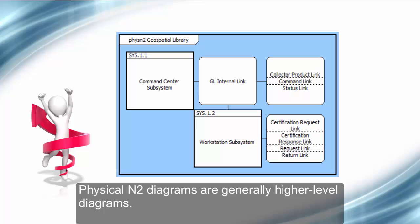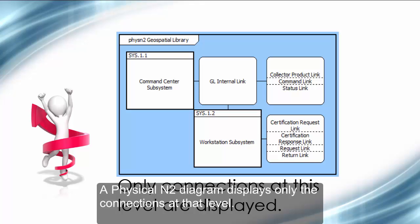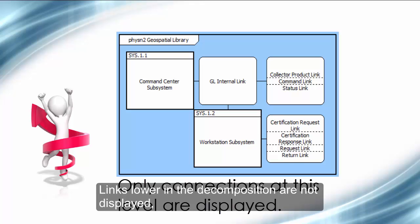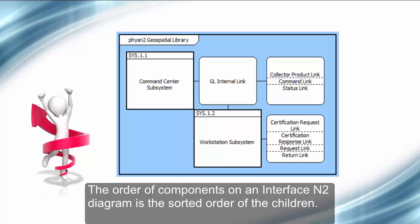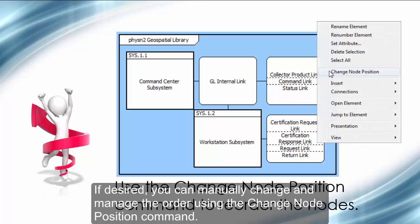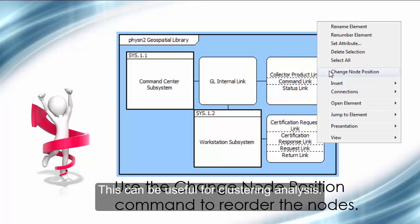Physical n-squared diagrams are generally higher-level diagrams. A physical n-squared diagram displays only the connections at that level. Links lower in the decomposition are not displayed, nor is the decomposition of components considered when placing a link in a cell. The order of components on an interface n-squared diagram is the sorted order of the children. If desired, you can manually change and manage the order using the Change Node Position command. This can be useful for clustering analysis.